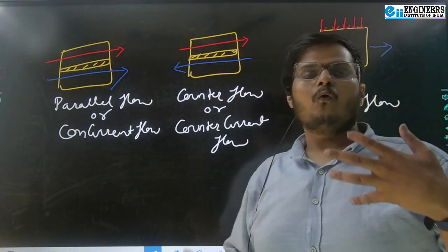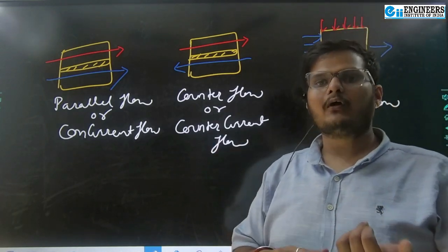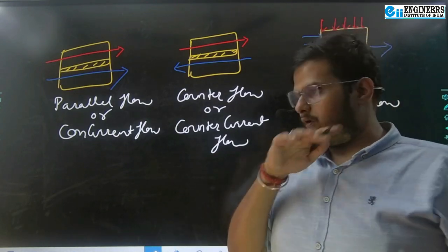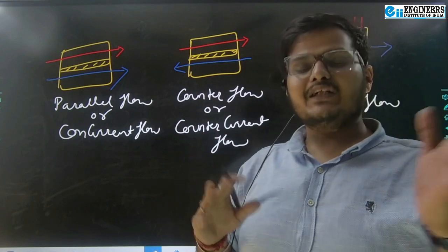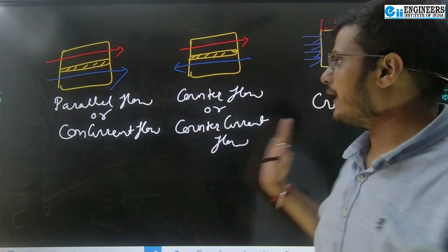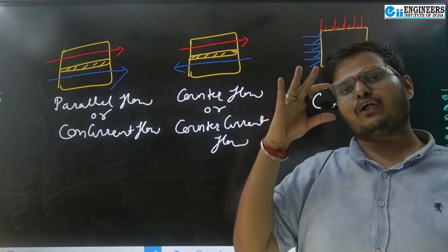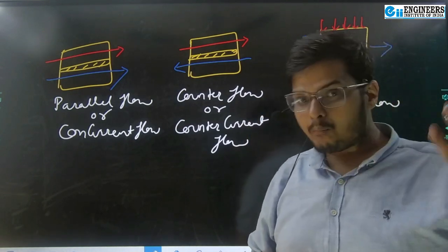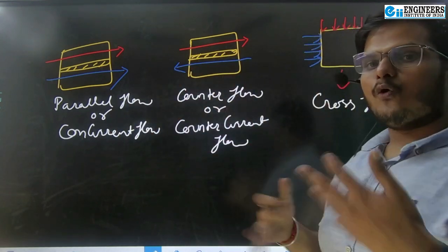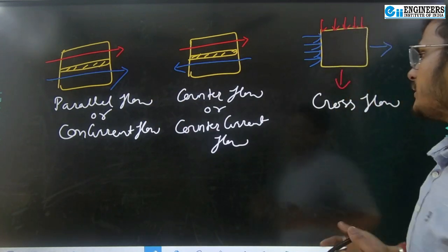Now if someone asks you to discuss the types of heat exchanger, based on the flow: parallel flow, counter flow, cross flow; based on the design: double pipe, shell and tube, or it can again be explained as regenerator, recuperators, and direct contact type. So the classification of heat exchangers is done now, but here comes in the double pipe heat exchanger, or the shell and tube heat exchanger, or the plate type heat exchanger, flow can be either parallel or counter. Cross has its own specific configuration of heat exchanger. That example also we will discuss subsequently.